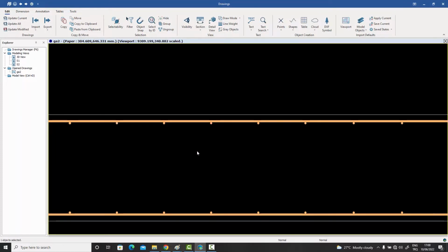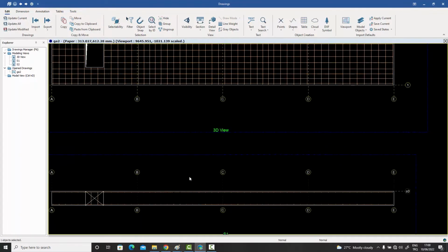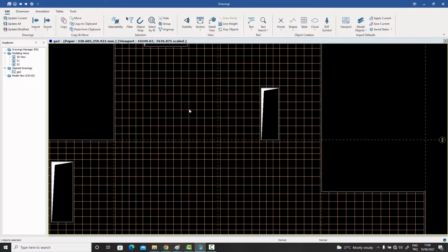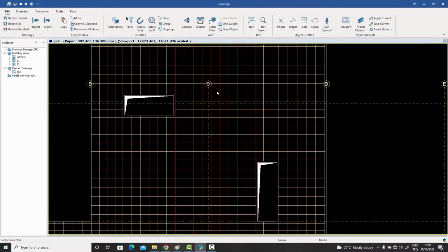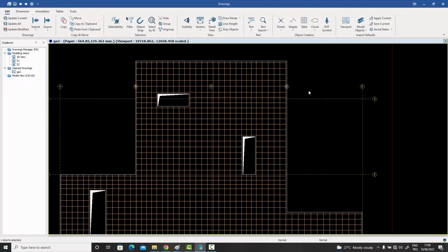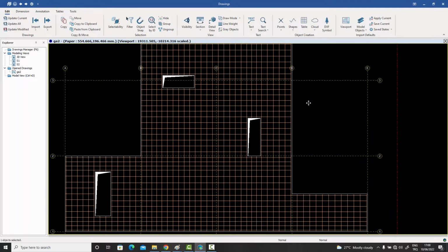This is very typical of reinforced concrete. When you're working in sectional views, you're basically looking at them in the form of either dots or lines. And when you're looking at them in the plan view, you're looking at them in the form of many lines. So this particular position goes from here to here, with whatever the position number is. Once I have imported it like that, I can obviously not leave it like that. I need to annotate it.